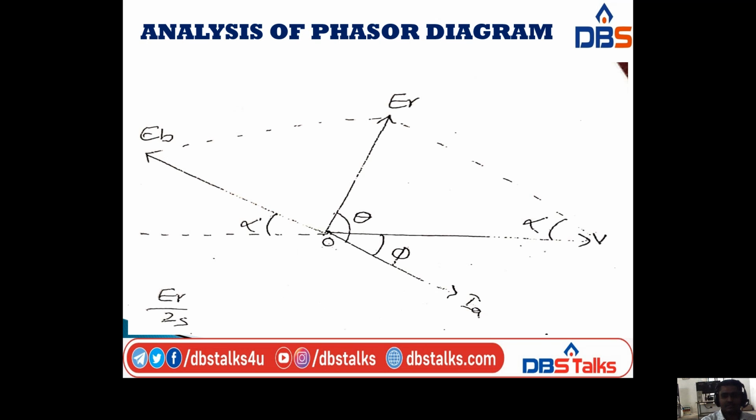Next, coming to the analysis of the phasor diagram for the previous concept. Here I am taking the voltage phasor as a reference, and Ia lags V at an angle phi, leads the back EMF at an angle alpha, and leads the resultant EMF at an angle theta.